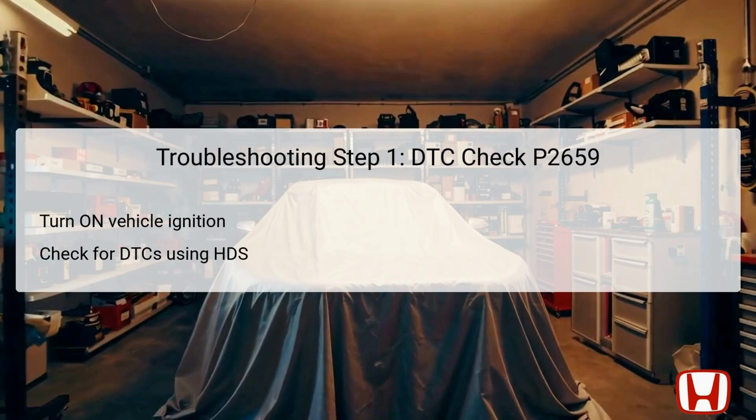The first troubleshooting step involves checking the status of Diagnostic Trouble Codes, DTCs, using the Honda Diagnostic System, HDS. To begin, the vehicle's ignition should be turned to the on mode without starting the engine. This action powers the vehicle's diagnostic systems, allowing the technician to check for both pending and confirmed DTCs.